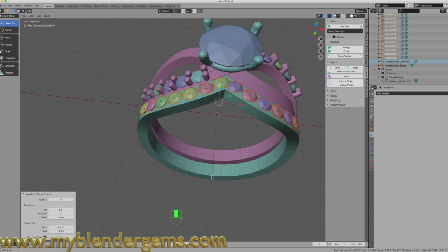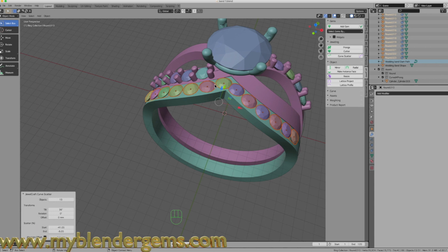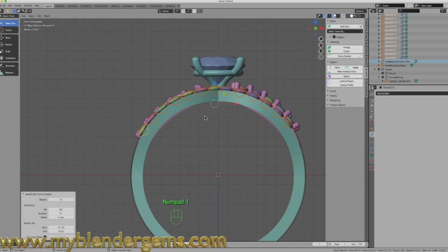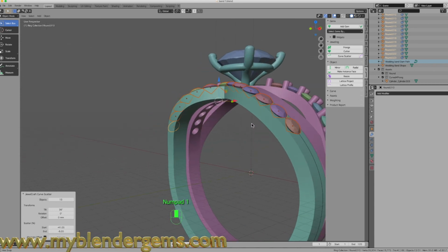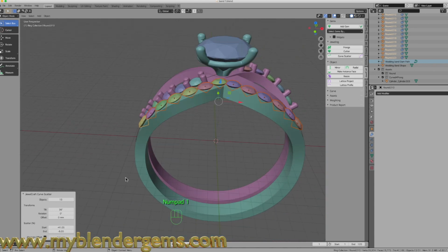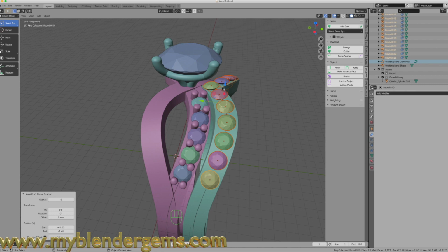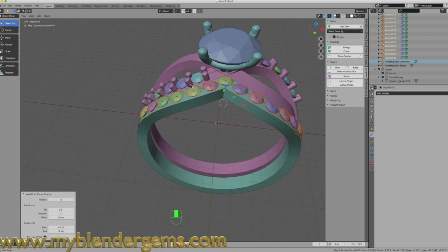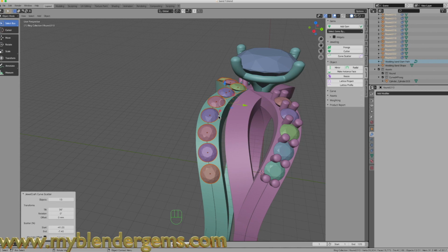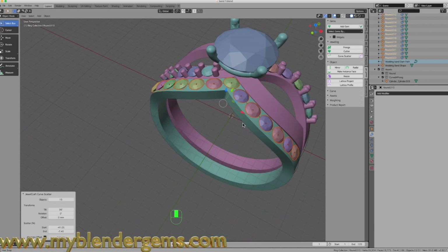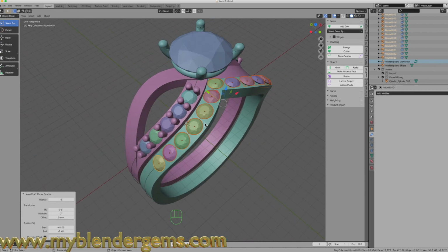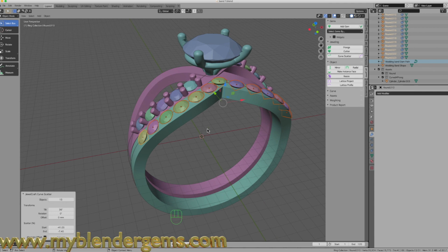location. And that looks pretty good, except I'm a little offset on the middle. I have 13 diamonds and they're not quite in the right location. So I'm going to move the end point over until I get that diamond right in the middle, right about like so. And now I've got my diamonds placed along this archway on the wedding band, and it looks like I'm in good location. So now it's time to add in the prongs to our wedding band.